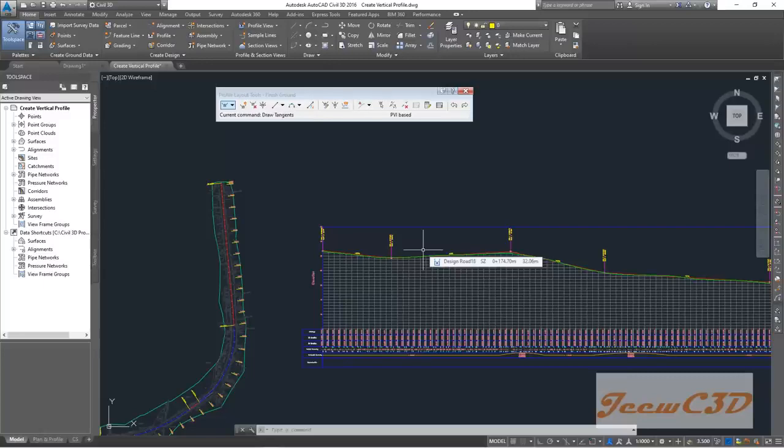If you are using a cut section, you have to ensure that it will not create access problems to the nearby houses. Also, high fill locations should not cause access problems to other nearby houses because of the road. And when you are having cutting sections, you have to ensure that you don't have culverts or flood issues when you are lowering the profile. You also have to consider the flood values when you are designing the alignment.